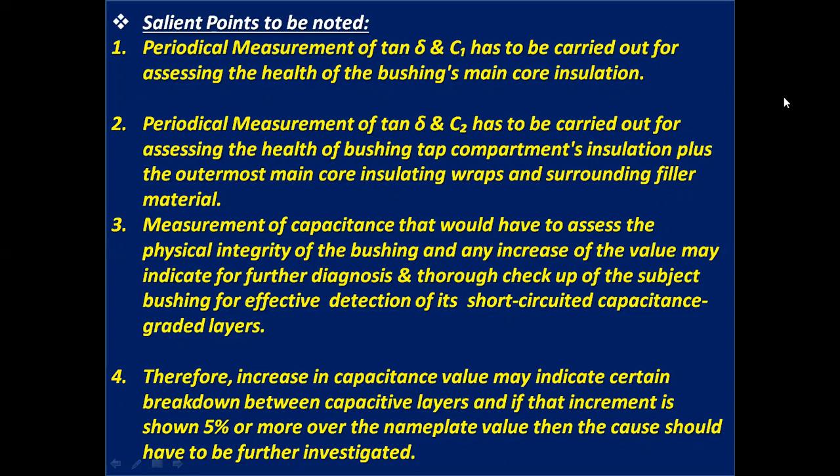Number 3, measurement of capacitance would assess the physical integrity of the bushing, and any increase of the value may indicate the need for further diagnosis or thorough checkup of the subject bushing for effective detection of its short-circuited capacitance graded layers.